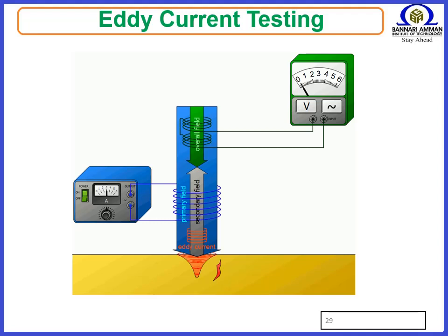Alternating current field measurement, ACFM, uses a specialized probe that introduces an alternating current into the surface of the test piece, creating a magnetic field. In parts with no discontinuities this field will be uniform, but if there is a discontinuity open to the surface, the magnetic field will flow around and under the discontinuity, causing a disruption of the field that can be detected by sensors within the probe. The resulting feedback can then be fed to software that can determine the length and depth of the discontinuity.